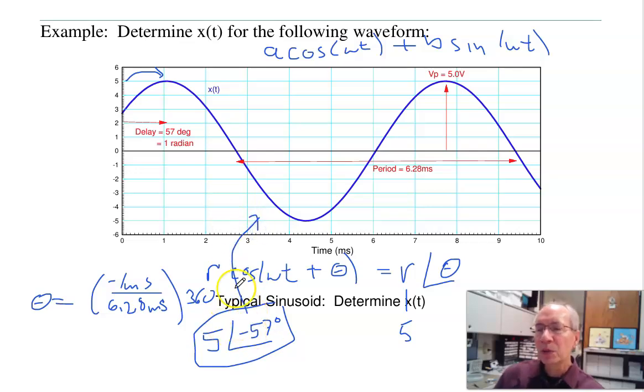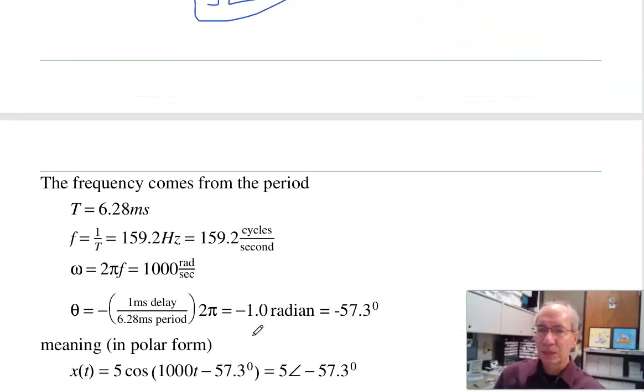And notice that polar form is kind of what you get in lab. I can see the polar form on the oscilloscope. The peak is the voltage, the delay is the angle. Now from complex numbers, this also has a real and complex part, rectangular form. That'll tell you cosine and sine. This, to me, is easier to see.